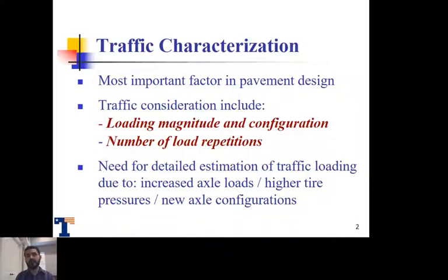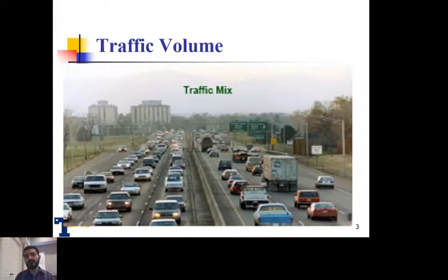The 18 wheelers, again, are known to have dual tires or tandem single dual tires, but now with the bigger trucks, we have what we call the super heavy load trucks. We have new, different axle configurations, including up to 12 tires per axle sometimes. And so we need to know those new axle configurations to include them in our pavement design.